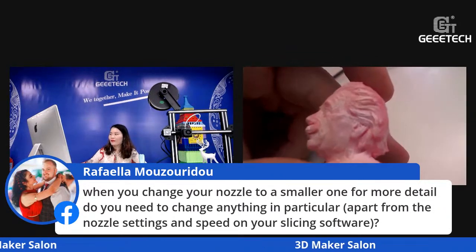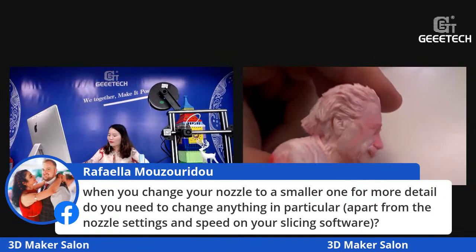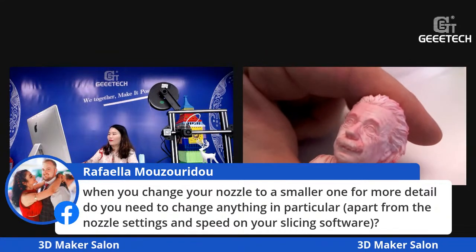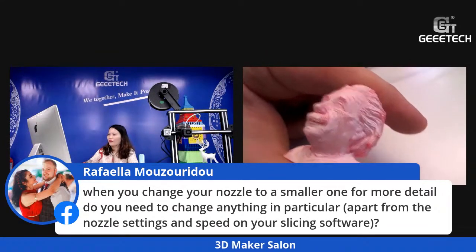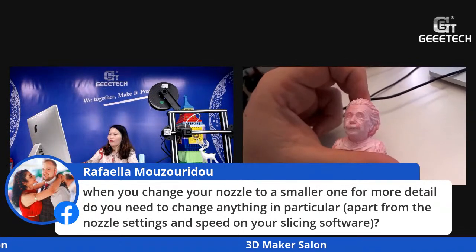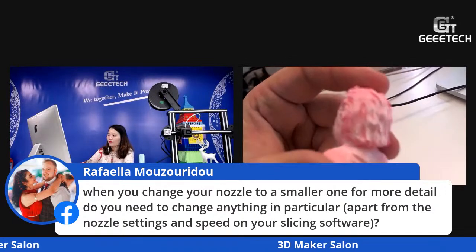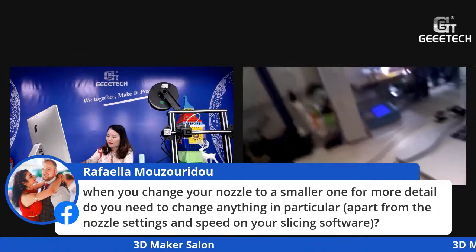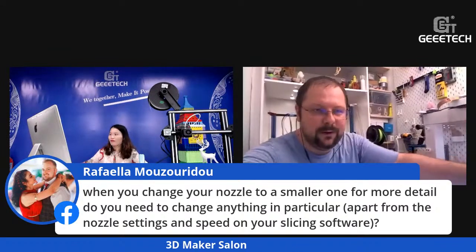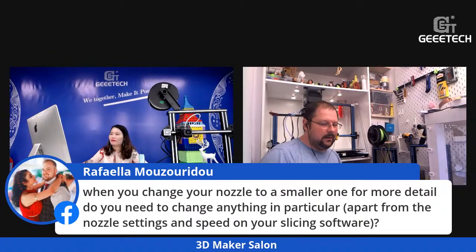This is great detail which you cannot achieve with 0.4 millimeter nozzles, only if you reduce the nozzle diameter. Here you can also see the pupils of this little figure. I think it took about 5 hours to print this little model. But as you can see, the detail is very, very good. So the short answer: no, it is enough to change the nozzle and the nozzle diameter in your slicing software.